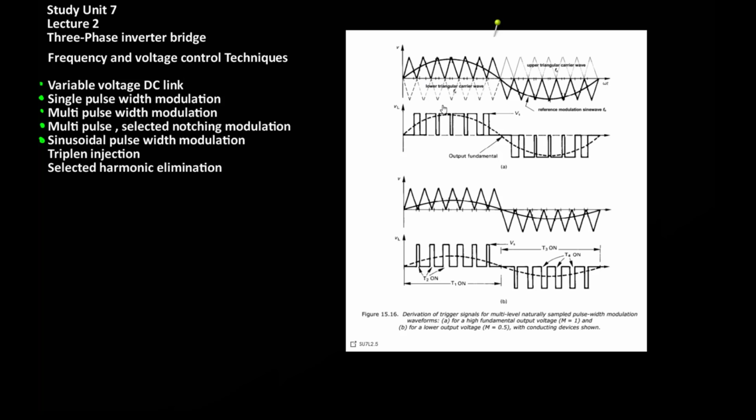So as can be seen here, much like many pulse width modulation schemes, there is a distinct difference between the pulse train generated by the high amplitude sinusoid and the pulse train generated by the lower amplitude sinusoid. One of the advantages of such a system, if implemented correctly, is that the commutation losses which would normally be present can be reduced, and the control circuitry can also be made quite simple.